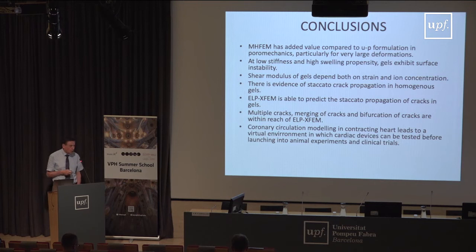This is ongoing work, and as a conclusion, I would like to tell you that mixed hybrid finite elements have added value compared to the normal UP formulation as available in Abaqus, for poromechanics, particularly for very large deformations, but also for non-homogeneous media. At low stiffness and high swelling propensity, gels exhibit surface instability.